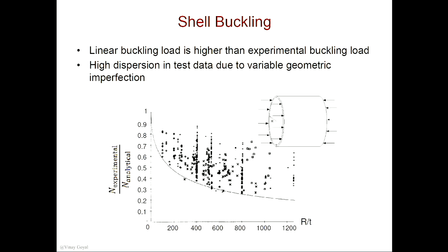And so for that reason, we need to figure out why there is that discrepancy. And that discrepancy, again, has to do with imperfections in the shell. Okay? Imperfections in the shell. And why do the experiments vary that much? One could ask that question. Why are the experiments all over the place? Anybody know? Because every shell will have different imperfections, maybe. Not one shell will have the same imperfection. And so for that reason, you will expect a discrepancy.